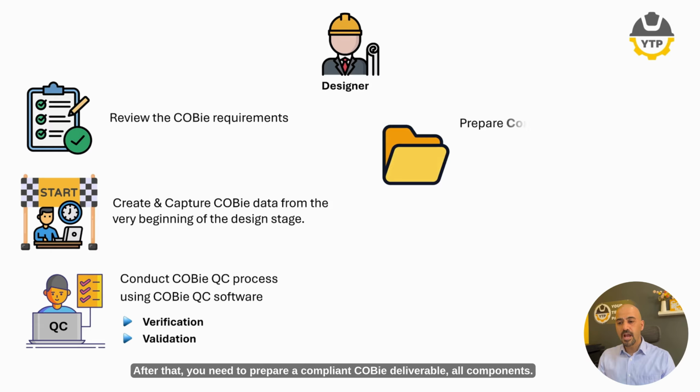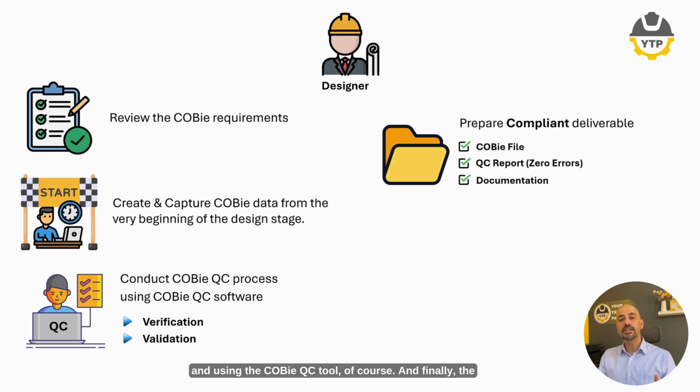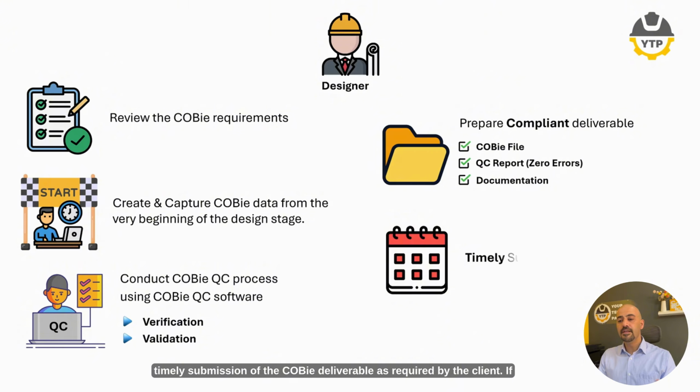After that, you need to prepare a compliant COBie deliverable, all components: the COBie file, the documentation, and the QC report showing zero errors, and using the COBie QC tool, of course. And finally, the timely submission of the COBie deliverable as required by the client.